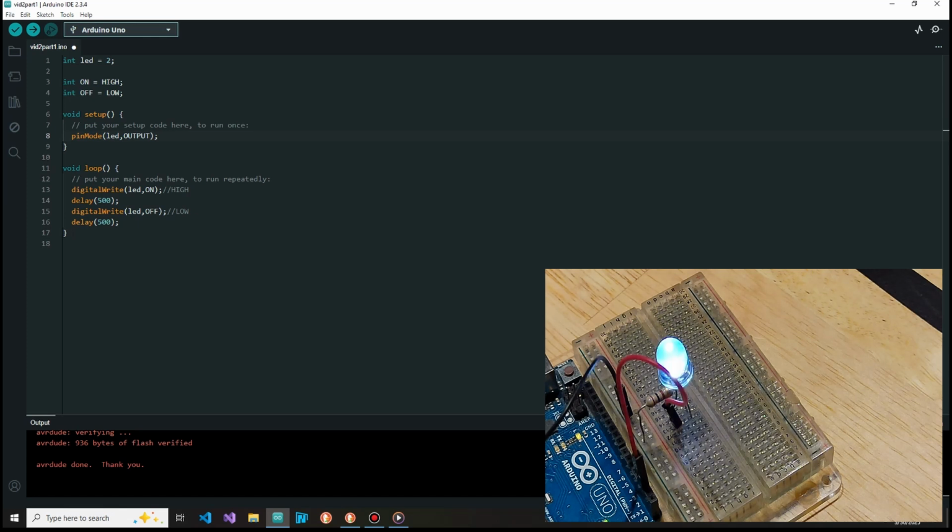So, when you are doing a function, we are moving the brunt of the code into a different section. In this case, we're going to call it void, because we're not returning any value back to the main loop. If we had to return a value back up to this, you're going to use something like these. So if we're going to return an integer, you would use an int here instead if you were returning information. We are not doing any of that right now, so we are just going to set up a normal void, and we're going to call this light, just to keep things simple.